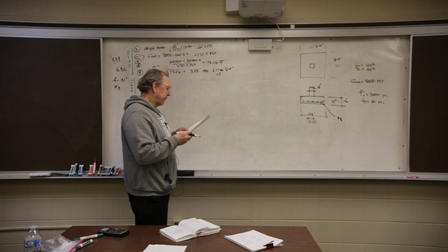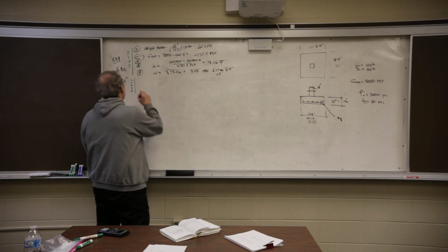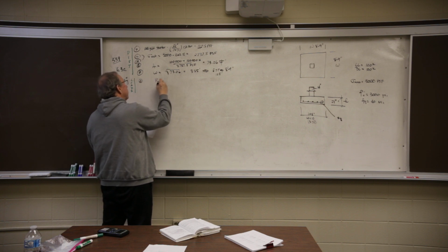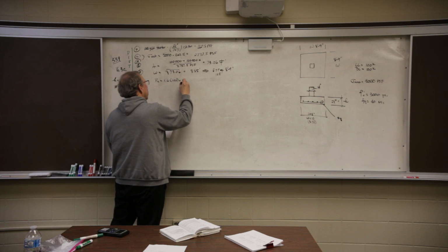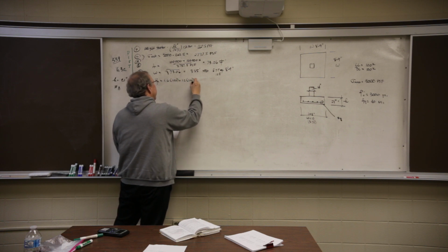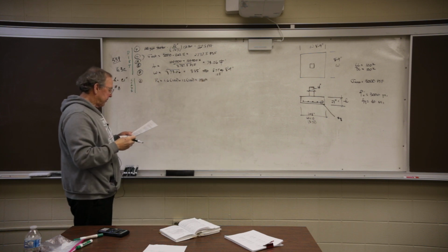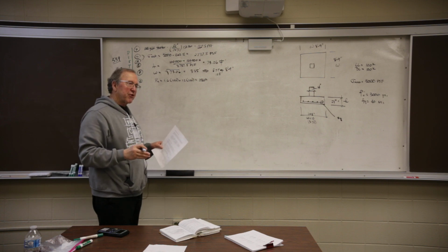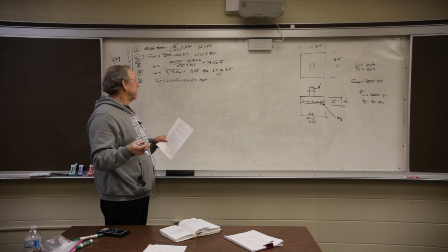To determine the reinforcement we need for the factored loads, you take PU. So I'm in letter I. PU is just 1.6 live, 1.2 dead. So we got 280 kips. WU is the amount of pressure pushing up by the earth after the loads have been factored.